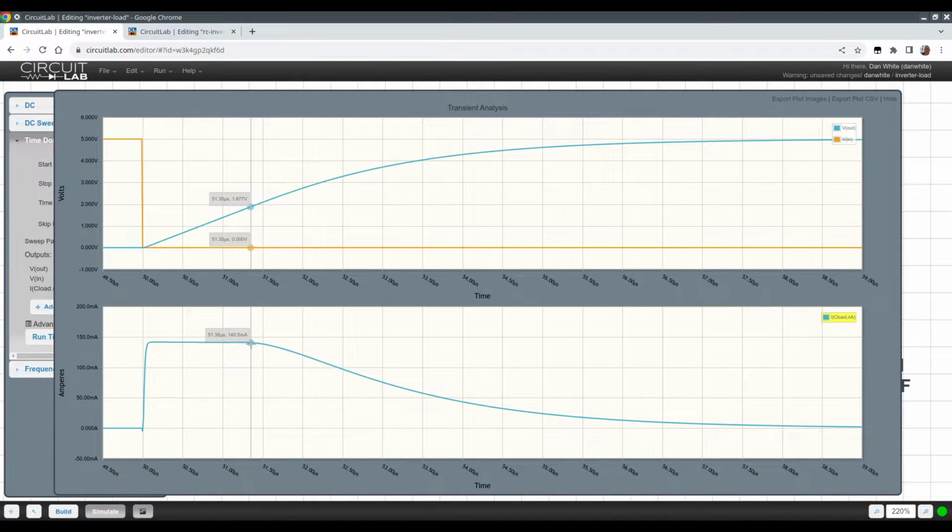When the current goes non-constant or starts changing again, then that means our transistor goes into triode mode from saturation mode. At that point, we're at about 1.87 volts, 1.8 something volts, 1.82 volts. Looking here and then looking up here, drain voltage, well, remember that was the threshold voltage of the CMOS MOSFET. Of course it is. All right. Constant current mode and then triode mode as we charge.